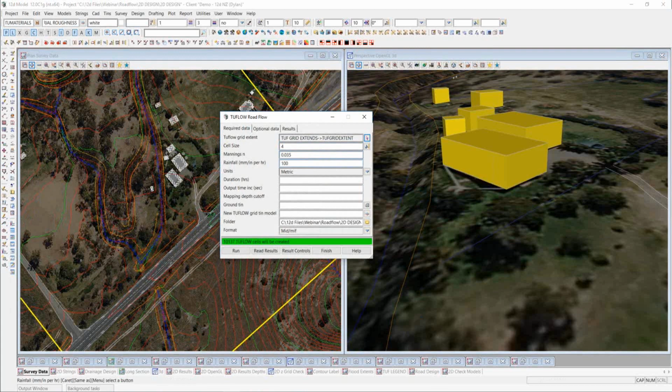I'm going to start off, our first example is just going to be a constant rainfall on grid. So it's going to constantly rain on every grid with an intensity of 100 millimeters per hour. I'd like the run to go for 0.5 hours. And these snapshot high-speed TMO files, I'd like to see the results every 30 seconds.